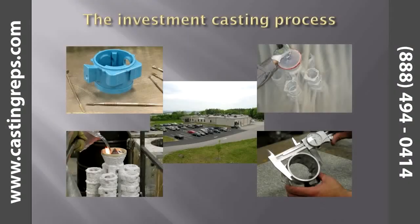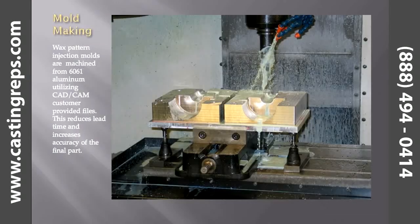The investment casting process. Mold making. Wax pattern injection molds are machined from 6061 aluminum utilizing CAD/CAM customer-provided files. This reduces lead time and increases accuracy of the final part.